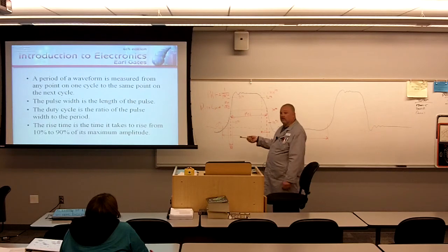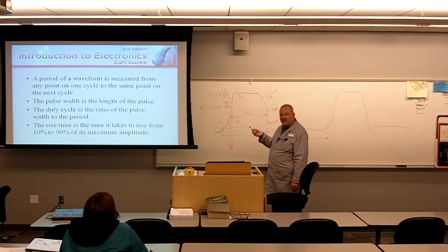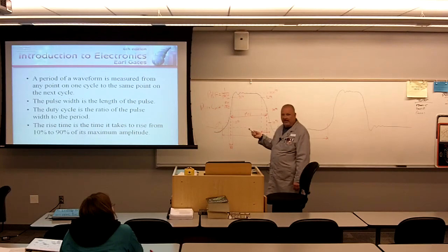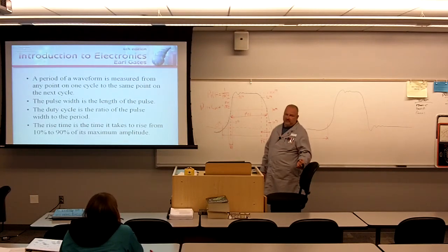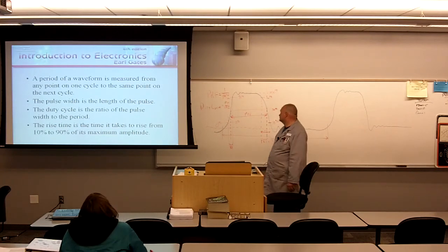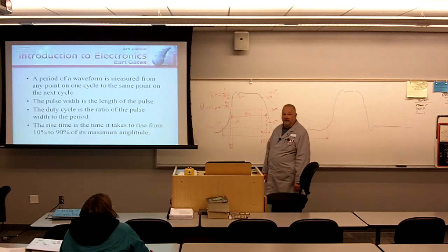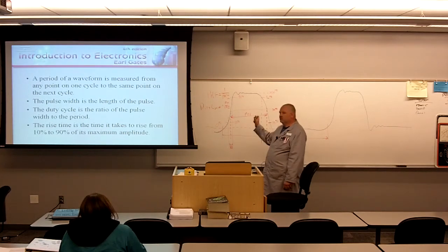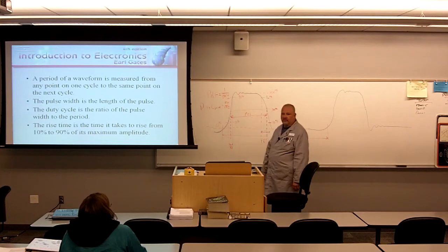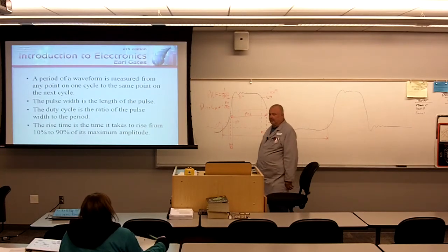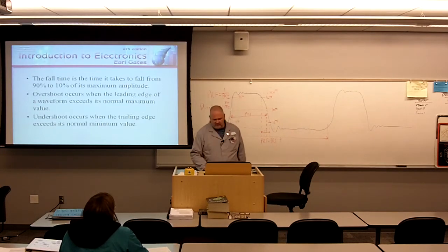You know what this also could look like? This could look like a pulse width of a waveform being sent to a fuel injector to squirt gasoline into a cylinder. It could be the exact same thing. It's all done with pulses. That would look pretty good for an automotive application going to a fuel injector. By playing with that pulse width, that's how much gas you're squirting into your intake. That's rise time, fall time.